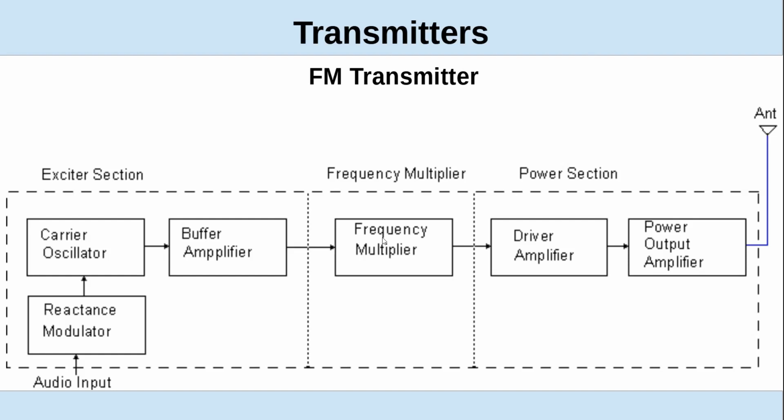Frequency multiplier is just a tuned amplifier that is tuned to a harmonic frequency. So if I had, say, a 1 megahertz signal coming in, this multiplier, if it was a 2 times multiplier, that's typical, sometimes you see 3, it would be a tuned RF amplifier for 2 megahertz. So it would see the harmonic of the input and amplify it and pass it on.